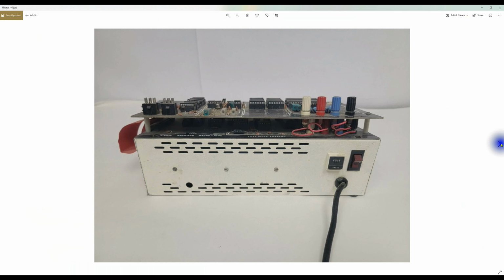Is there a better photo of those? Here they are, kind of from the back. I did some research and actually found new old stock of the connectors, the hoods, and found the pins on DigiKey. So actually working from the BOM, I was able to figure out what the manufacturer parts were here and actually buy the connector bodies for the female pins and the hoods. I had to go to a specialty place to find those.